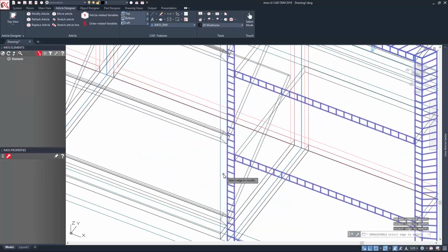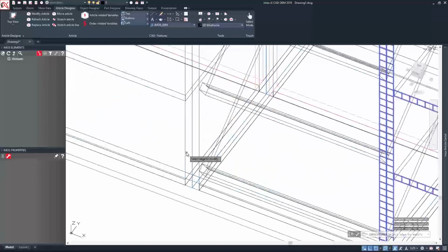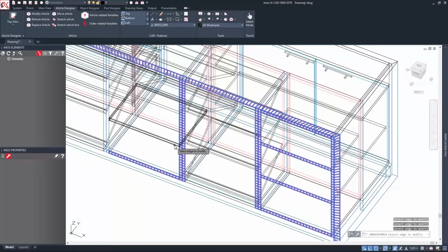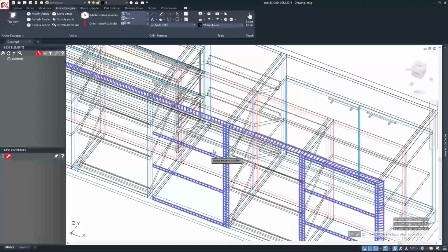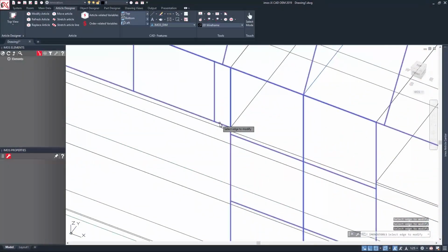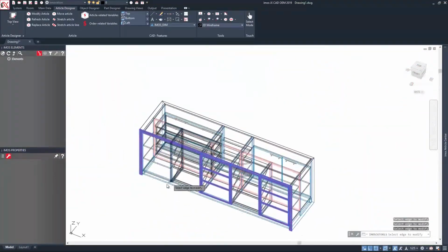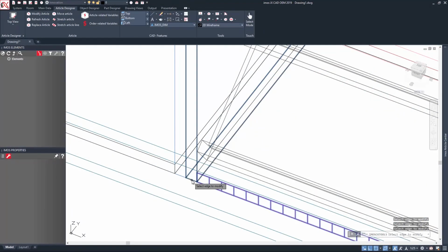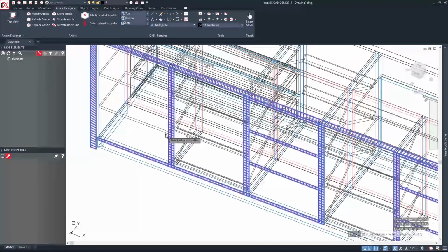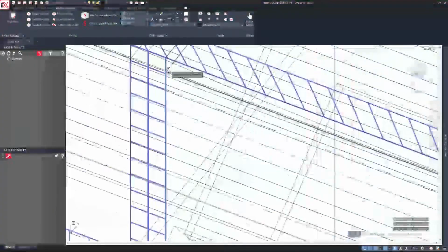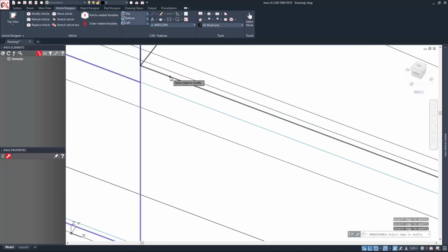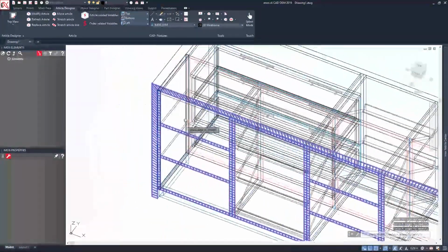pieces. Now what I won't be able to do is bring my angled shelves in line with my polyline, because that would then bend the melamine board in the wrong direction, which is no good. So I just need to omit them from the selection. So I'm just taking a little bit of time here, just going through selecting the edges that I know are going to be required for bending. So I also have this adjustable shelf, this far one. I think I'm missing one up here for my top shelf on this particular cabinet, and then one here.